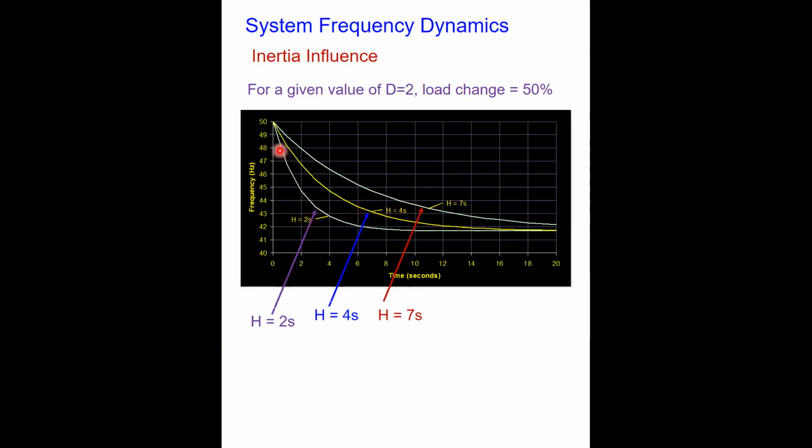So you find that if the system inertia is low, then you have a sharp decline, a sharp reduction in the frequency profile. Thus you can say the rate of decay in the frequency depends on system inertia as well. The higher the system inertia, the decay, as you can see, is comparatively less. And if you have low inertia, then you find more decay in the frequency.